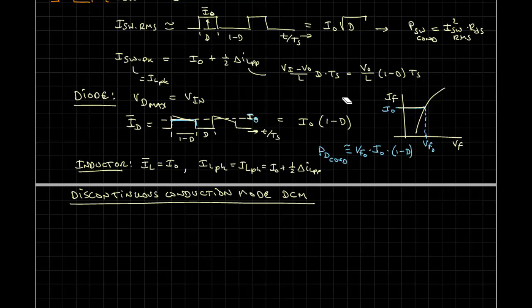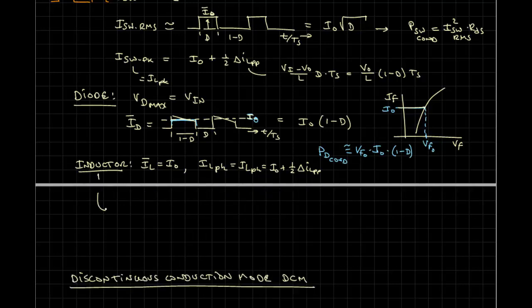When you pick your inductor, there are a couple of things you want to be careful of. For your inductor, you want to look at I squared R heating. So there will typically be an I_DC limit, and that's not because the core is going to saturate or stop acting like an inductor, just because there's too much I squared R loss.